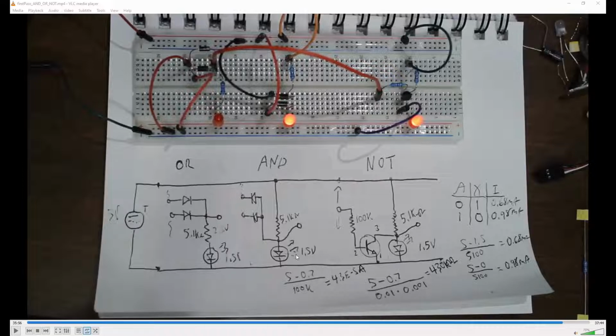Ideally, we want this 1.5 volts to rise to very close to 5 volts, so we want to add 3.5 volts. So we would choose a resistor that in this series circuit would result in this output being lifted to the 1.5 volts of the LED plus 3.5 volts voltage drop across an appropriately sized resistor. Let's play.